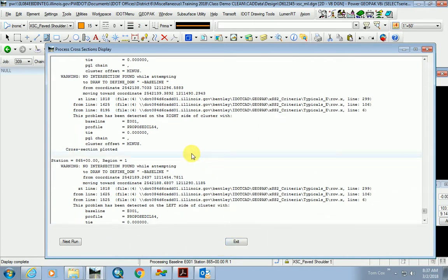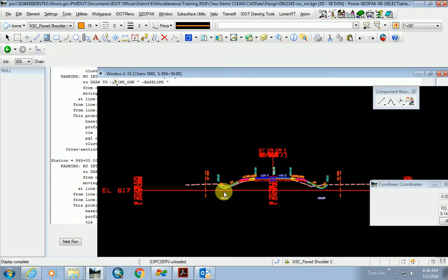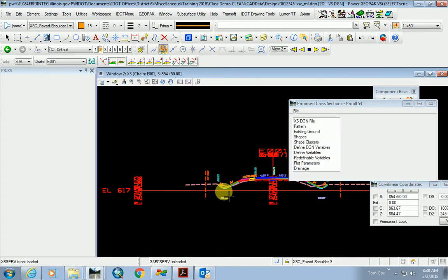If you ever get to the point where you just can't figure out what you did wrong, there are a couple things you can do. You could go to where that log file is and look through it, and it'll tell you what the problem is. The other option is, while I was processing, it gave me the option of reading the criteria viewer or something like that. I could have let it run through all that text and hit next. It's reading every syntax that it takes to do this, and it takes a while because there's a lot to go through. But I could see every single thing, and ultimately I would be able to figure out what the problem was.